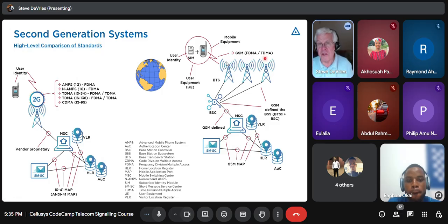It was frequency division multiple access, so you had different frequencies, but also you were divided up in the time domain. So you could share it with up to 7 other users, in time slots 0 to 7. They were very short, about 4 milliseconds. As you're speaking, someone else could speak at basically the same time, but you're assigned different time slots. So this was all standardized.